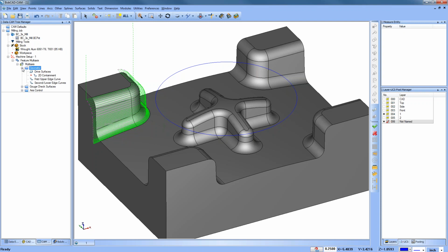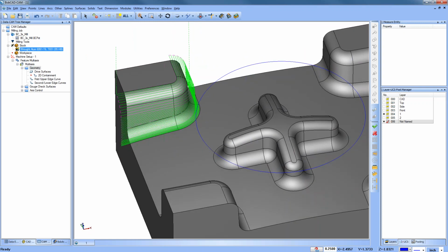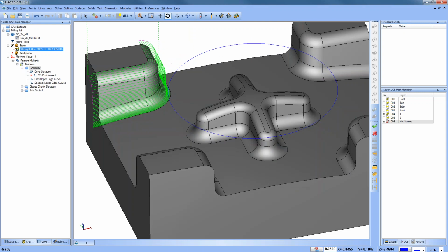George, yes, using the toolpath extension in the toolpath editor, you can get some extension in 3D. But you also have to look at the geometry type that you're after to see what's going to make the most sense. A lot of times I'll just extend the geometry. So this is a quick way to extend out your toolpath without having to edit any geometry. Okay, so that's a morph strategy there.